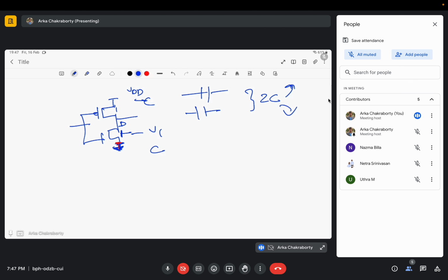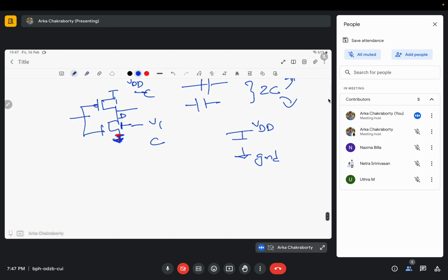See, when you're designing a circuit, what is capacitance? We are trying to find the capacitance between my final VDD and ground. I want to find the net capacitance. Basically this is a black box with many Rs and many Cs, and I want to find the resistances and capacitances. There are five capacitive terms due to the things that I already mentioned. There are other capacitances like interconnects, because simple metals are not used generally. You use different metals like titanium, nickel and so on. They introduce interconnect capacitances.